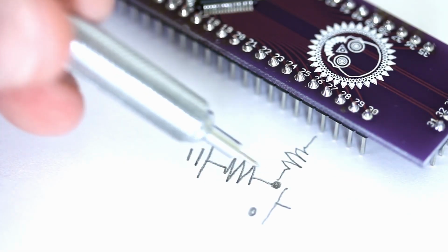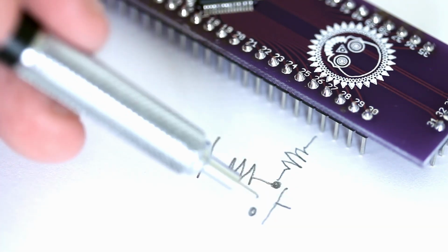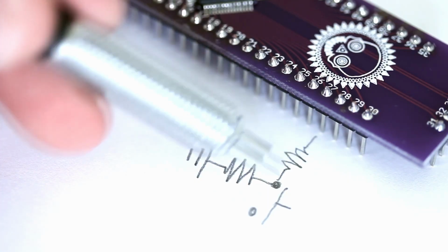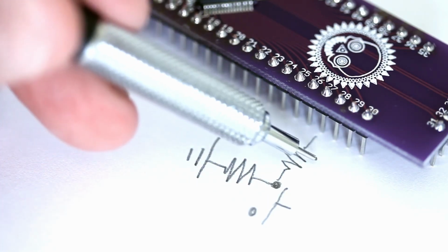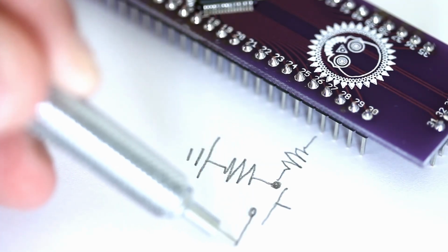And the ground resistor will be at a high resistance, so we're not going to be using a lot of current when the switch is actually depressed. This will be a 220k ohm resistor. The resistor coming from the pin will be a 330 ohm resistor. And this resistor really is only to be used when this is going to be connected to VCC.